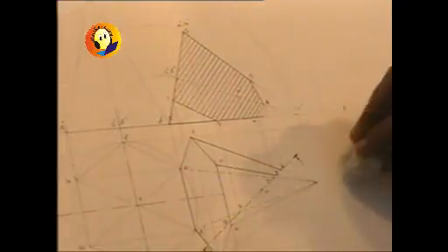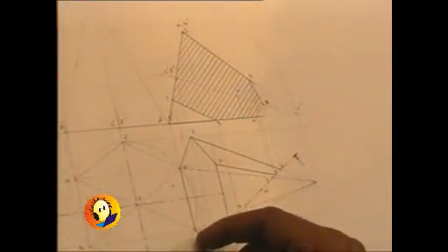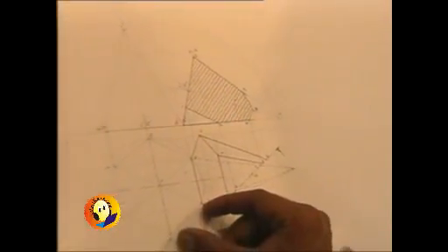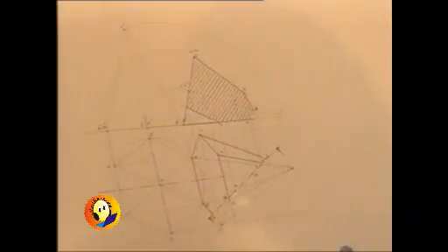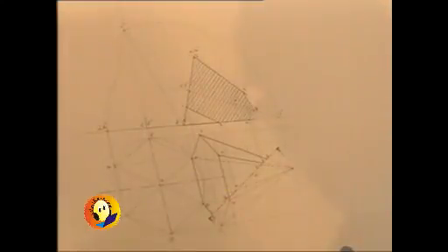Now for the development, we are required to have the true lengths of all the sides. We know that there are going to be in all 6 triangles, and those triangles are having the base of the triangle as the base of the hexagon, and the other 2 sides will be the true lengths of the generators. All the generators which we have over here, AV, BV, CV, DV, EV and FV, they have got the same length. Question is whether we have their true length with us, and you will find that none of this generator is parallel to XY, and hence we don't have the true length of any of the generator.